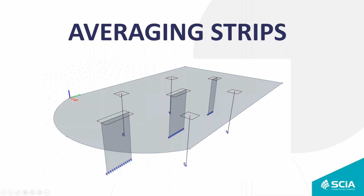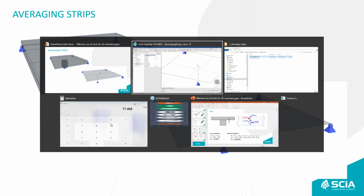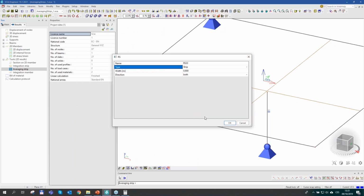Of course, if there is an intersection of a slab and a 1D member, such as a column, most likely I'm going to use the averaging strip, the point one, while when there is an intersection between 2 walls or 2 slabs, and there is a risk of peaks, then I'm going to use strip. So let me get back to SCIA Engineer environment.